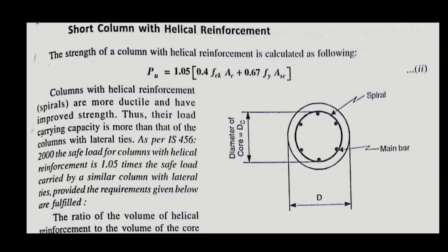Okay, that's why this is called helical reinforcement. So this kind of arrangement is actually called helical reinforcement. Before reading it out, let's check the IS code consideration. For helical reinforcement, the IS code consideration is given in clause number 39.4 of IS 456/2000.